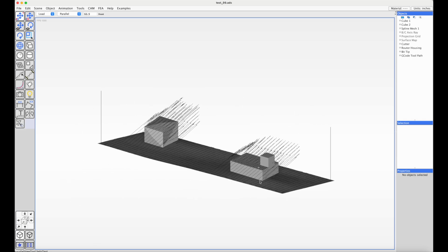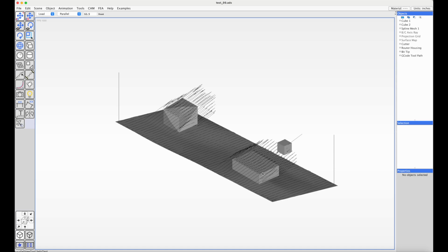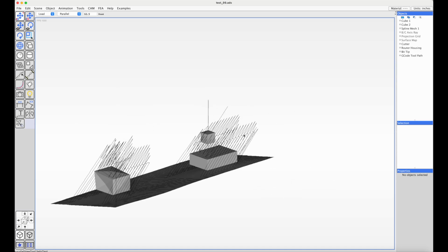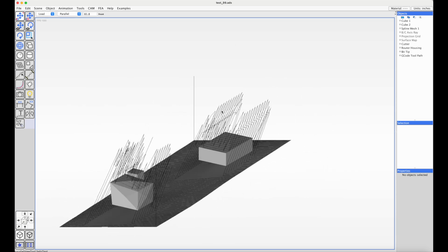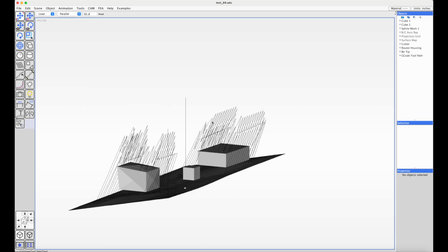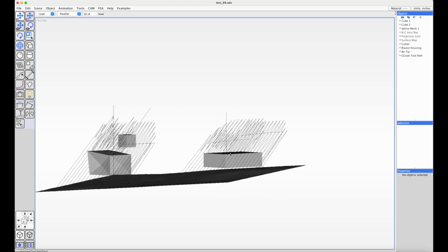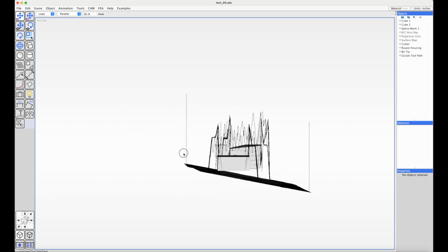So anytime it gets to a spot where it can't get the tool in, it pulls back on the axis that the tooltip is pointing based on the B and C axis. It doesn't necessarily need to run these jagged edges. This is just a demonstration or a prototype concept.